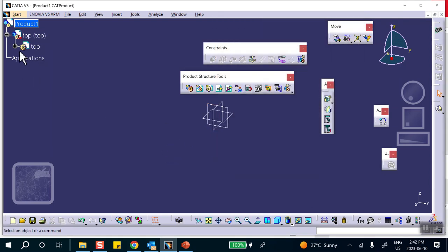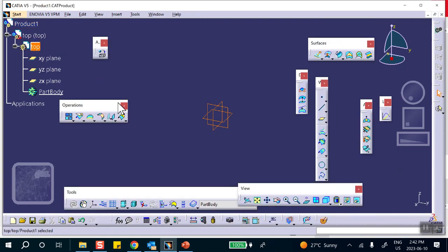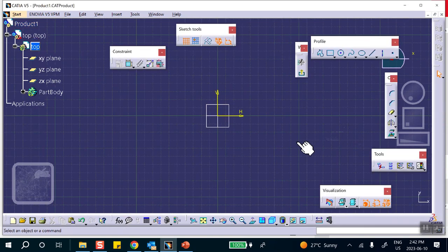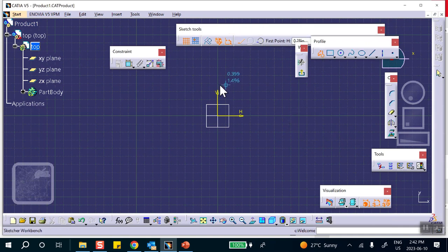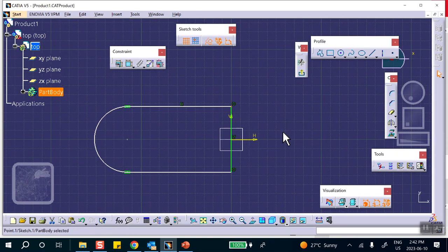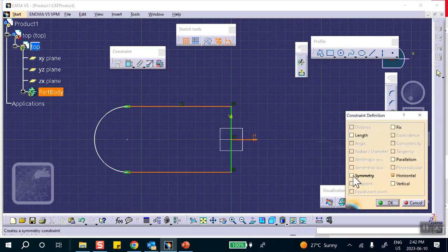Okay, let's make it. Double click on that plane. I will sketch half of that shape that you see there. So it's going to be like this. We'll clean it up in a minute. Something like that, and like so. Okay, first of all, let's clean it up. This top line, control, bottom line, control, the middle axis. It's going to be symmetric.